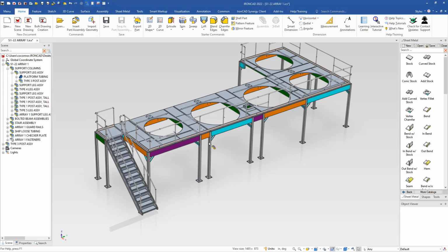So a very handy tool to restructure your tree, and that will work with parts or assemblies. For example, we can select this one, do the same thing on our assembly. We can do a Control-X to cut it, select on the assembly where we'd like to place it, but this time we actually want to move it below that platform tubing, so we'll just do a Control-Shift-V below that, and notice it'll come below that part in the scene browser there.